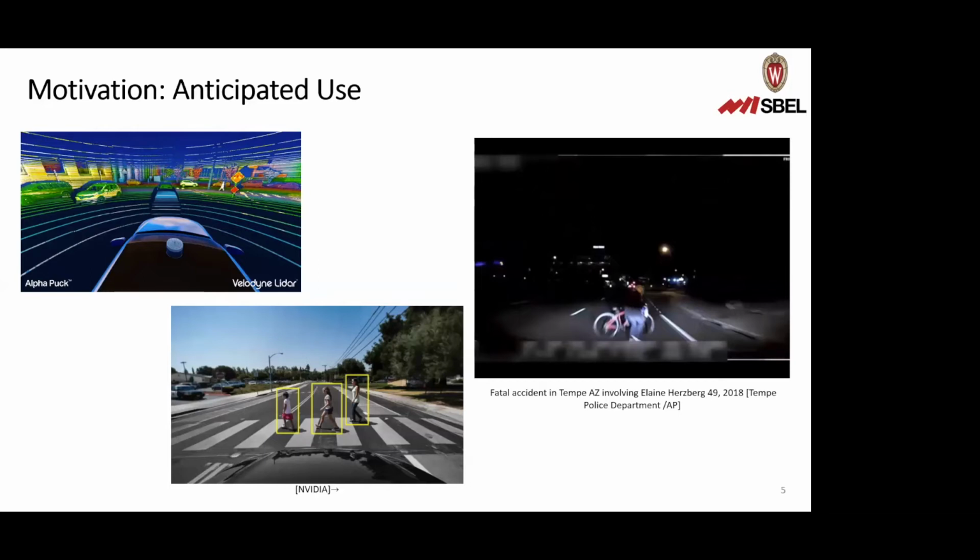And a couple examples here. The left two are what's heavily used in perception in AVs. The top left is data from a LiDAR. And this can basically be used for localization of a vehicle, but also for object detection. So if we're trying to detect pedestrians, we might want to simulate this first so that we have an idea that we can detect pedestrians at a certain success rate, before we try to put this in use. The bottom is, again, the same thing, but for a camera.